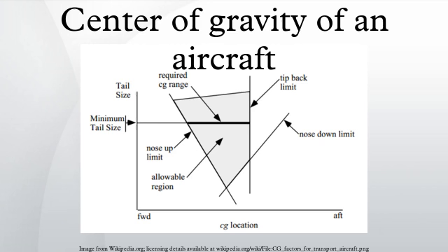In addition, with an extreme aft CG, gusty or rough air could accelerate the helicopter to a speed faster than that produced with full forward cyclic control. In this case, dissymmetry of lift and blade flapping could cause the rotor disc to tilt aft. With full forward cyclic control already applied, the rotor disc might not be able to be lowered, resulting in possible loss of control, or the rotor blades striking the tail boom.